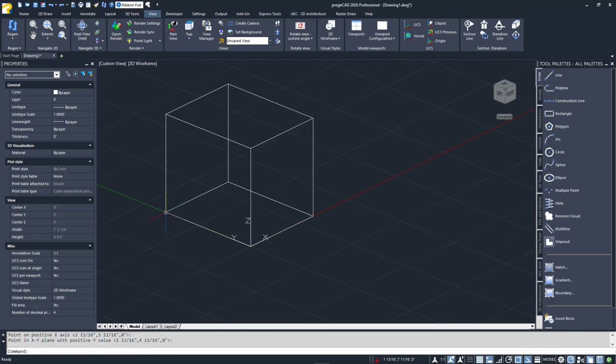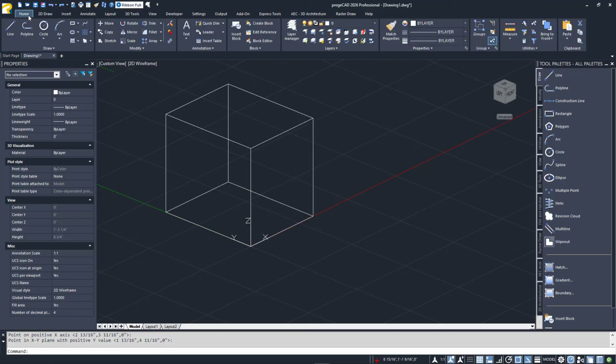The Z direction is calculated. The new UCS will display at the new origin point. Now, I can easily draw diagonal lines on the face of the box I defined. To return to the WCS, I can click that icon in the ribbon or select World from the UCS box just below the view cube.